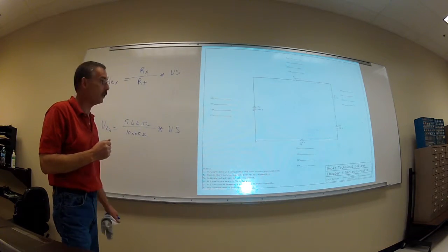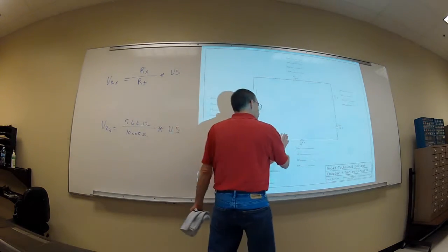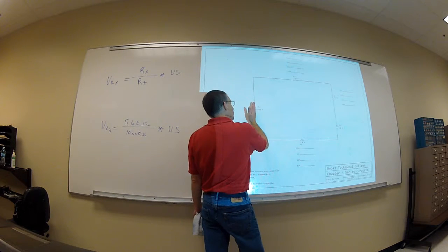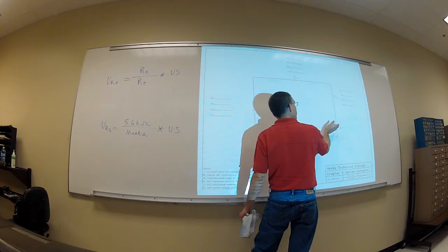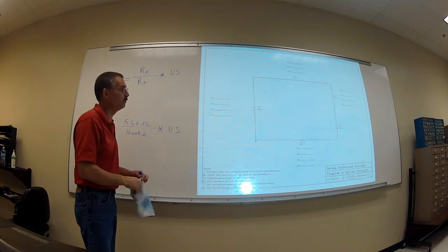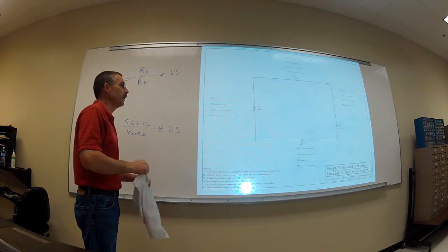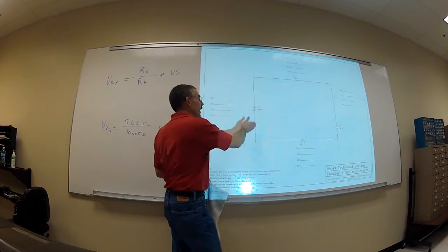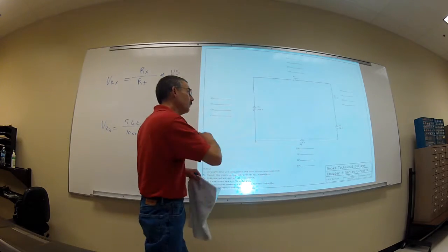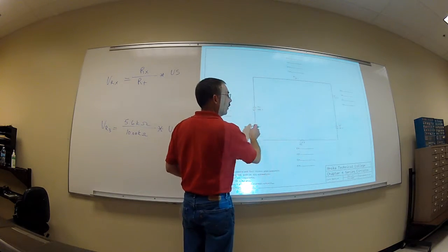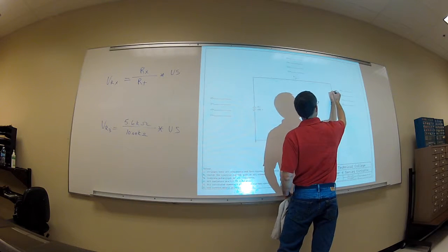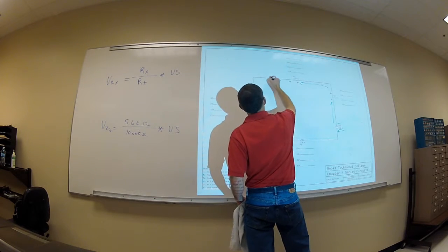So that's one thing to remember: when we're analyzing circuits, sometimes it's hard. We look at a circuit, and we've got this power supply here, but then there's another power supply between another couple of components, and we're trying to figure out, is it a series circuit? Is it a parallel circuit? Is it a series-parallel circuit? We just have to realize that just because something's not what we normally see in our worksheets, we just have to analyze it. If I draw in the current path, we know the bully on the block is this one here, so we know that my current is going to be going up here, and then we just draw in our current path. And then you analyze the circuit the same way.